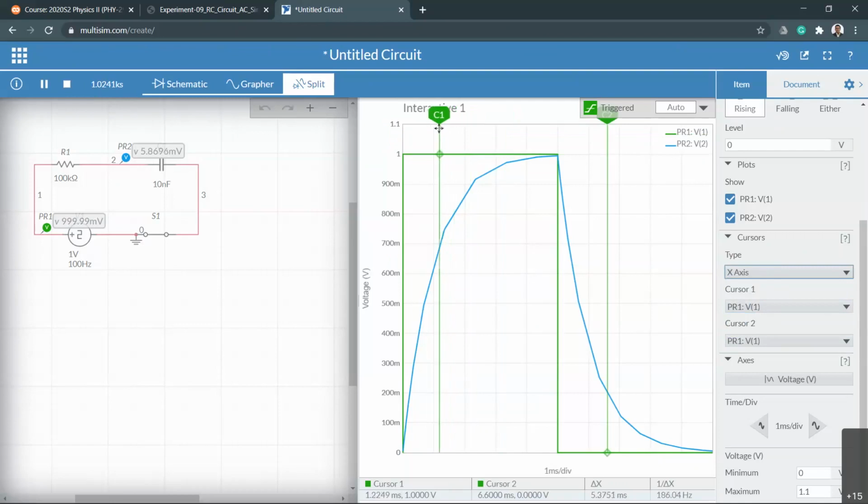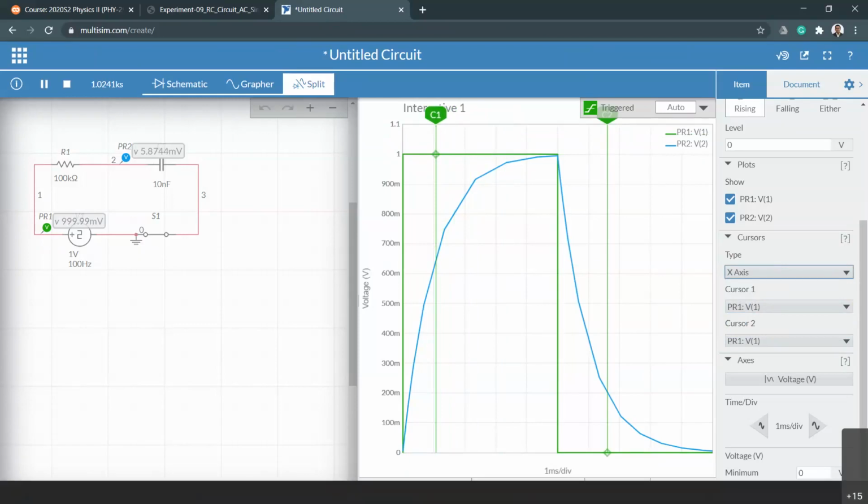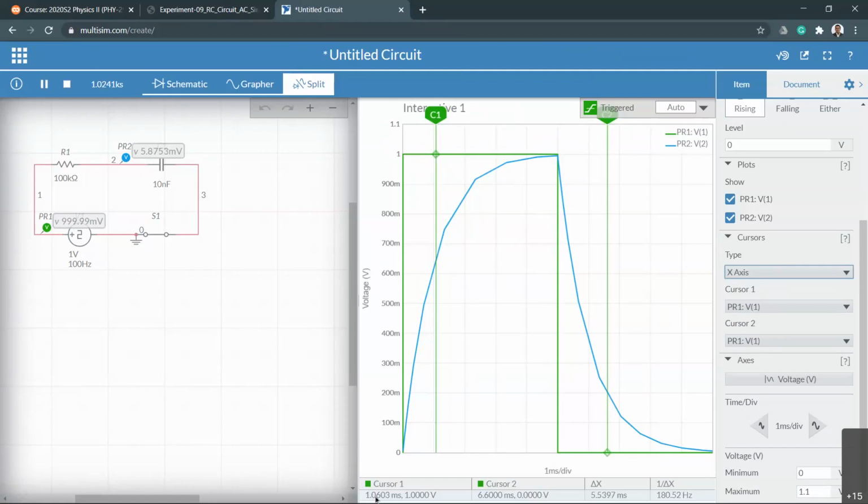I want to read exactly. You remember earlier the 6.3 is very close to here. Okay, you have to pinpoint that point and then read accordingly. So the time axis right now is going to be about 1.03 millisecond. So that is actually the division value right here. Okay, each division is 1 millisecond per division. Make sense? Following?